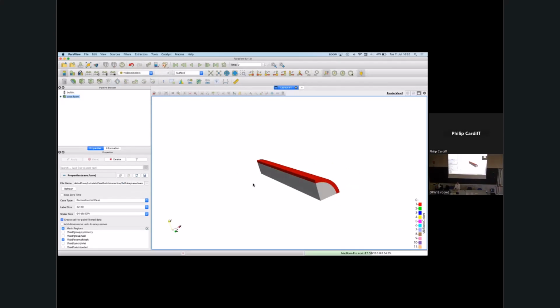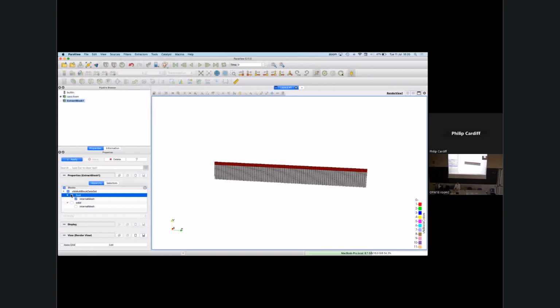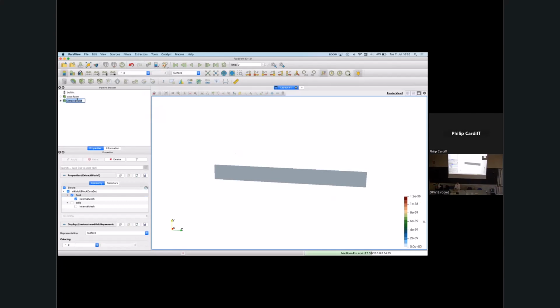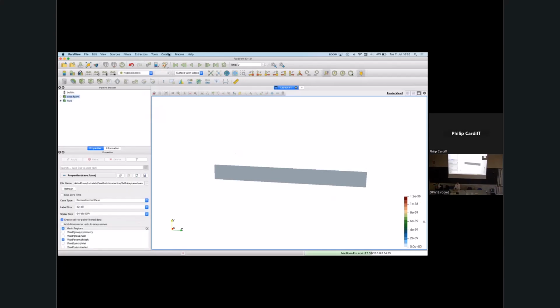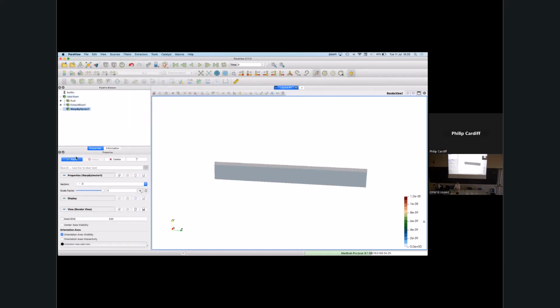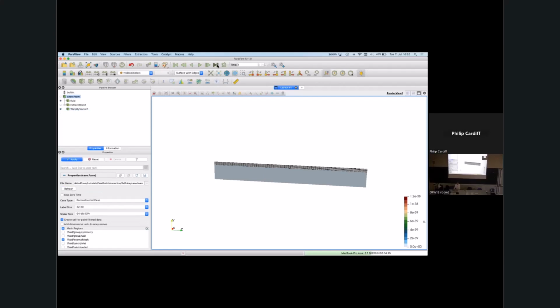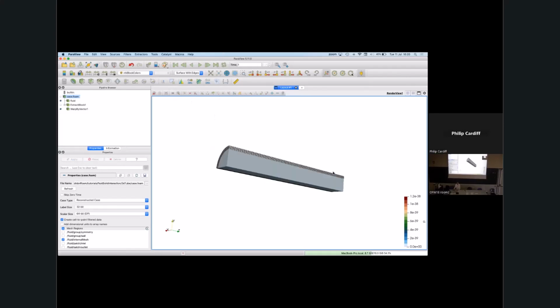Okay, so this is the test case. It's 3D, we're using symmetry planes. I can extract blocks again, so I can extract my fluid. I can extract my solid. And it's a small strain approach here, so I can warp the solid as well. If I refresh, I don't even know if we have any time steps here. No, okay. So there's nothing to show at the moment. But if you run it, it will run through and you can check the different results.